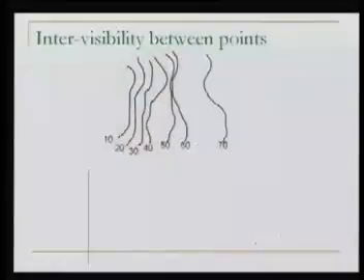So this is the problem of intervisibility, and we can solve this problem by the contour map, because contours mean the topography of the ground is there. How to do it? We'll do it by one example now. In this example, let us say this is the contour map where these are the contour values with a contour interval of 10 units. Let us say 10 meter here.